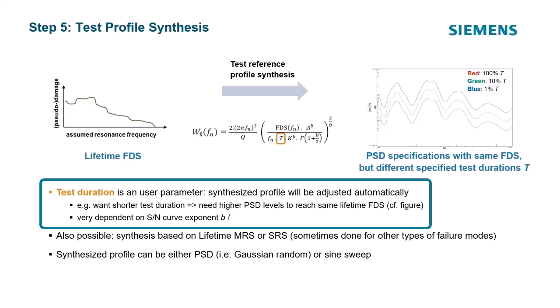Now, here's where it gets hard. Let's say it's supposed to survive 1,000 hours, and you can say, I want to do a 10-minute test. Well, it's probably going to be so high, it's not going to be realistic. You can say whatever you want. And then you've got to determine whether you over-accelerated the test. And that's the real engineering judgment in the mission synthesis or any frequency domain process.